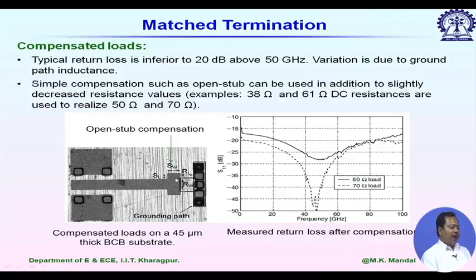Usually the fab lab will give you a standard thickness for that nickel chromium and standard resistance per centimeter. Then you have to choose a proper dimension. So, you know that resistance depends on length and width. So, accordingly you have to select your length and width to realize a given resistance value.